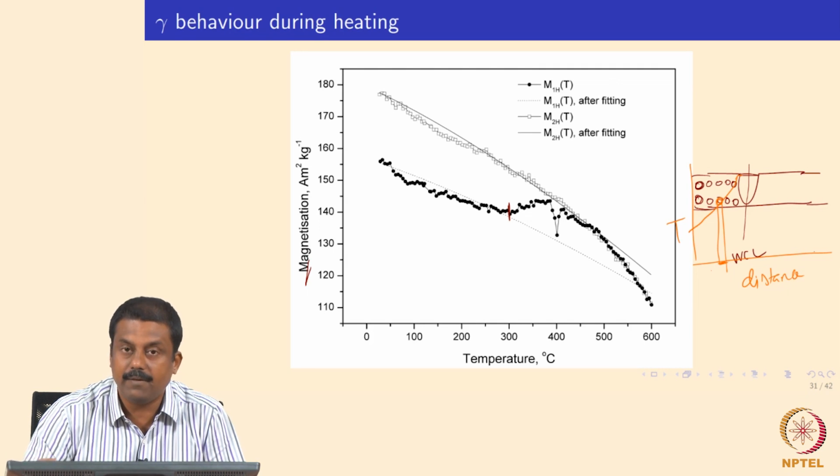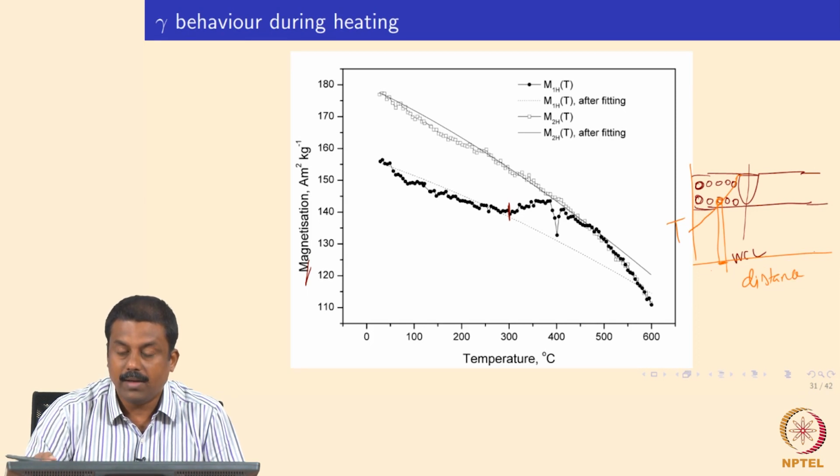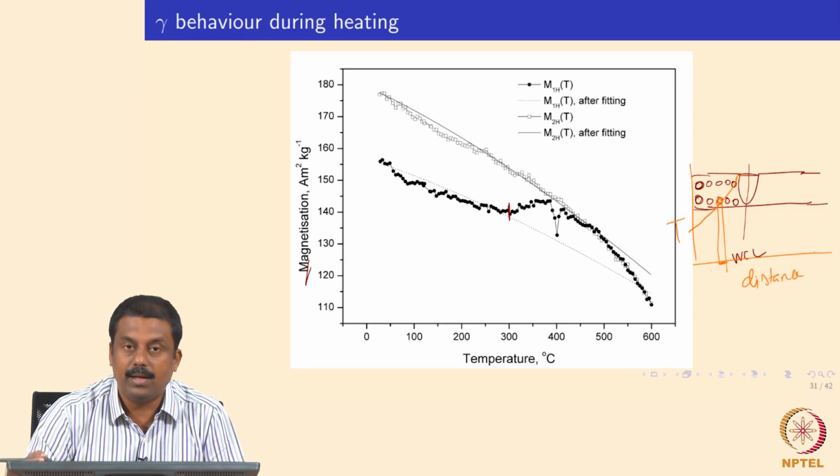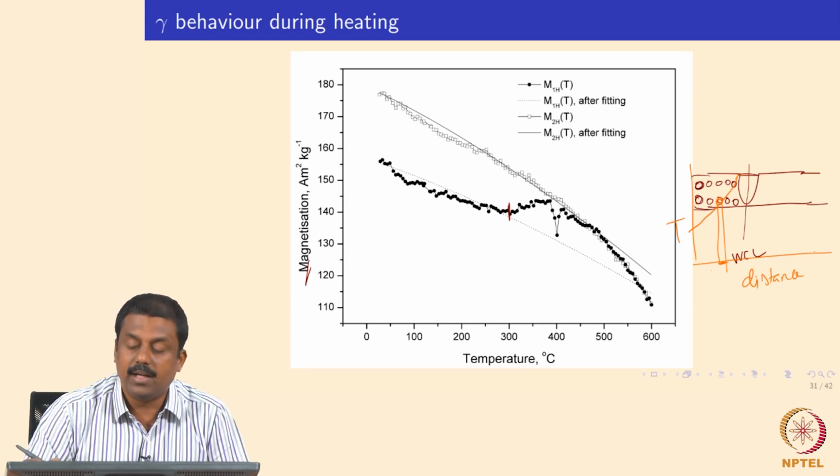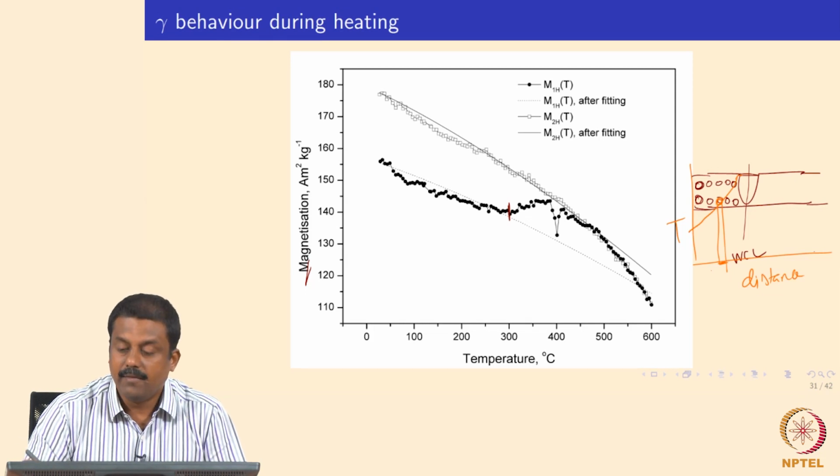That means the effect of peak temperatures is not clearly delineated. You are measuring the effect of a weld thermal cycle where the peak temperature ranges, say, from 800 to 900 degrees centigrade in one region. So, we need to measure much more accurately with respect to the spatial distance.